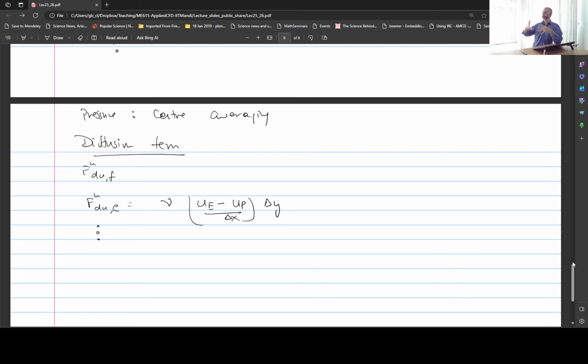Because if your boundary is an arbitrary shape, which it is in most cases, like an aerofoil of an aeroplane, then it's difficult to make rectangles and store because it's a curved boundary. So you have an unstructured grid so that it can take the shape of the boundary nicely by putting points along the boundary. Anyways, we won't say much more about that. That's for an advanced CFD course where you learn how to deal with that. But for this, I think this idea is enough.